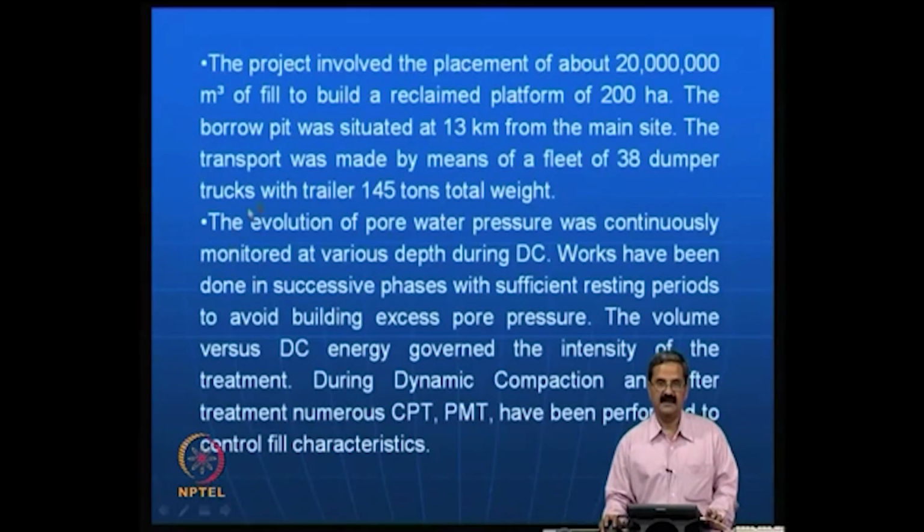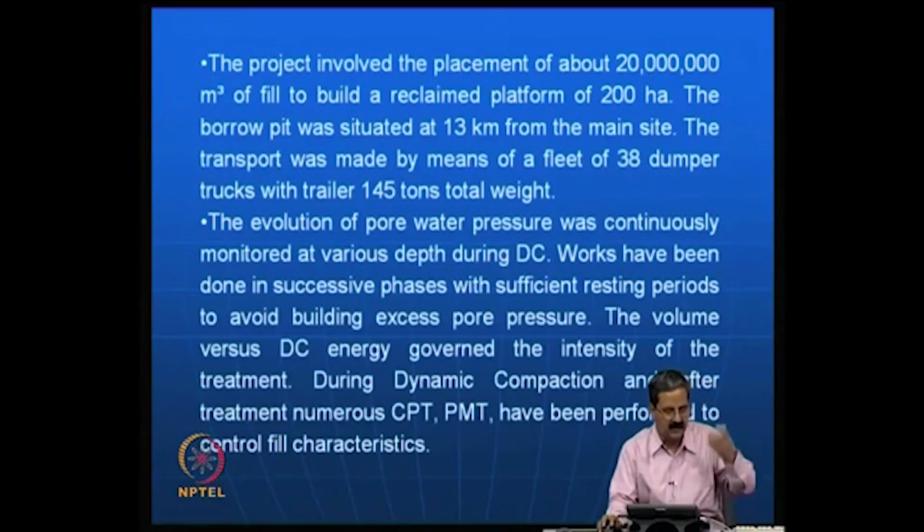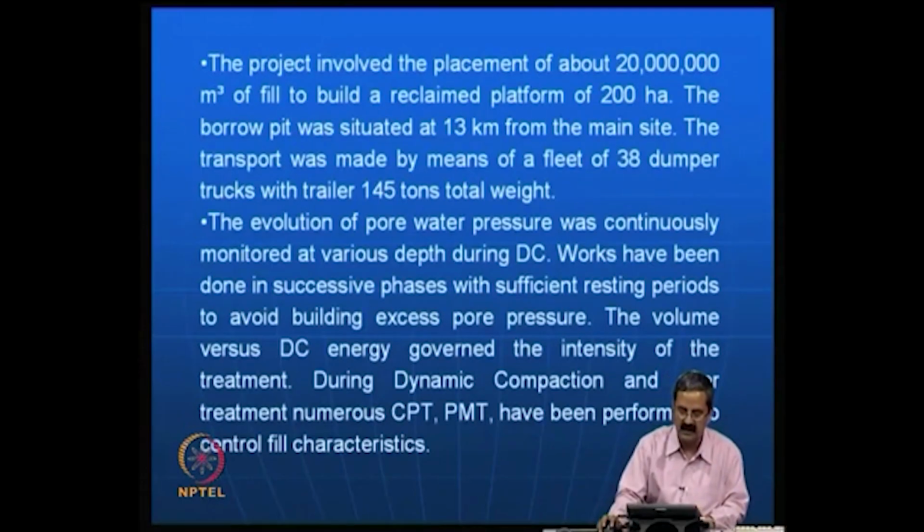So in this case, the pore pressure was continuously monitored at various depths during the dynamic compaction. As I just mentioned, the pore pressure variations during dynamic compaction play a very significant role in deciding about the construction, the tamping operations, the release of load and all that. The work in this case was done in phases with sufficient resting periods to avoid building up of excess pore pressure. The volume versus DC, or the dynamic compaction energy, governed the intensity of the treatment.